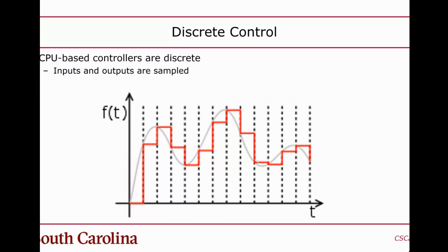And that's the whole problem: depending on the thing you're trying to control, if your computer that's implementing the controller is not fast enough, doesn't have a small enough sample time, then it's basically not going to work. But the problem is the mathematics are not going to help you, because you'll end up doing the transfer functions, the closed loop transfer function.